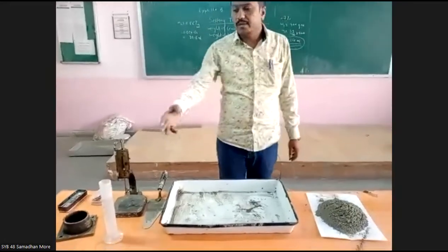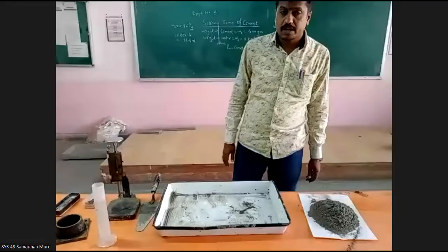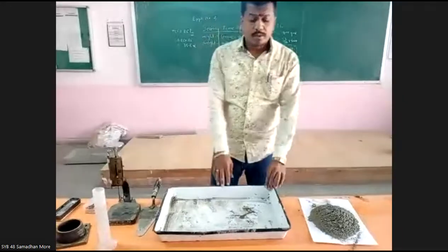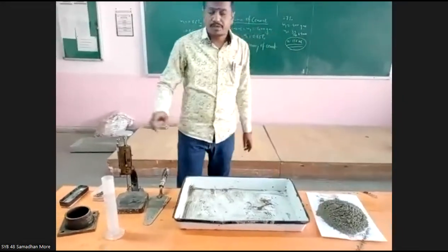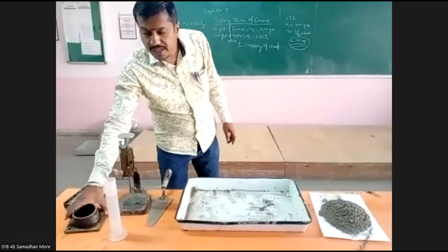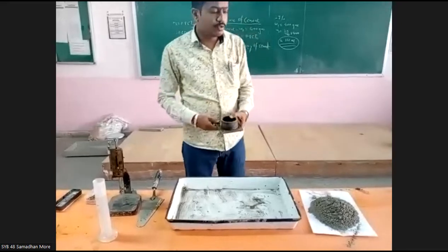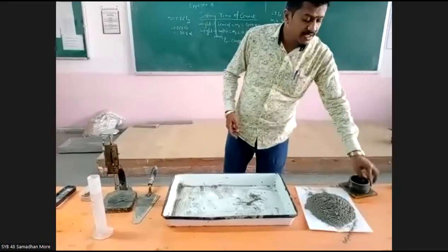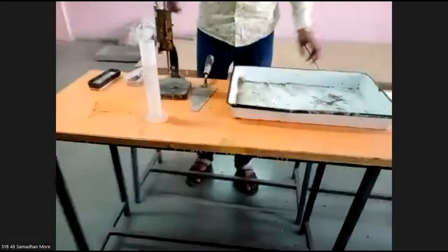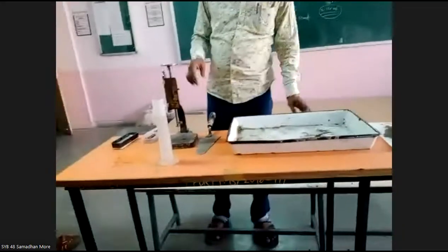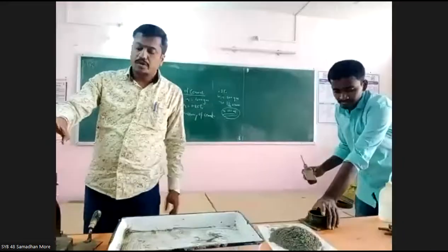Now, with the calculation, 100 ml water, we have taken 400 grams of cement already. Now we are going to prepare the mix. Again, we are going to prepare the cement mix, and then fill that mix into this particular mold. The dimensions you know, so I am not going to repeat them once again. Then you keep that mold in the Vicat apparatus.